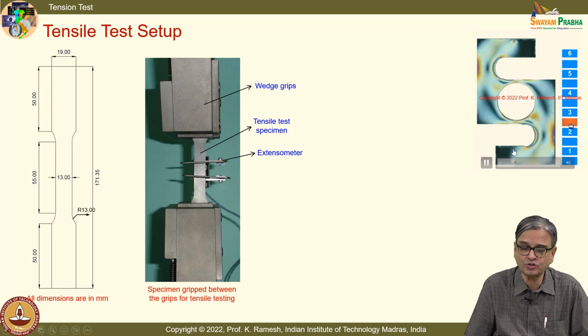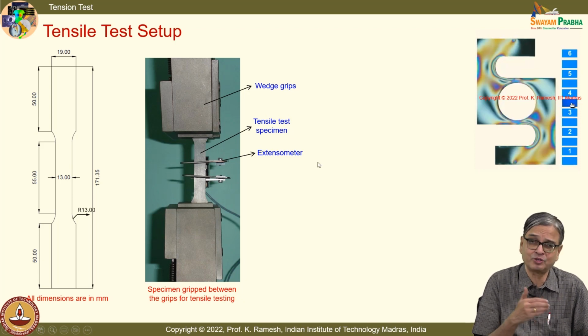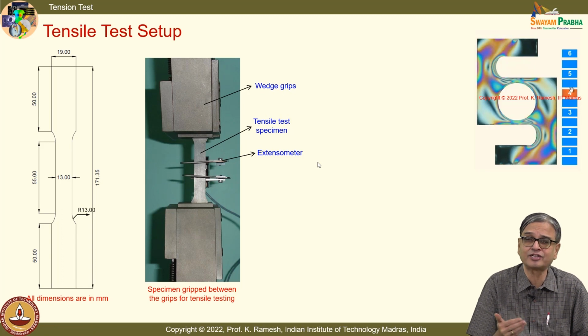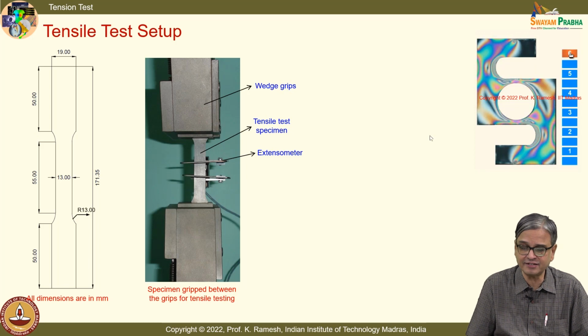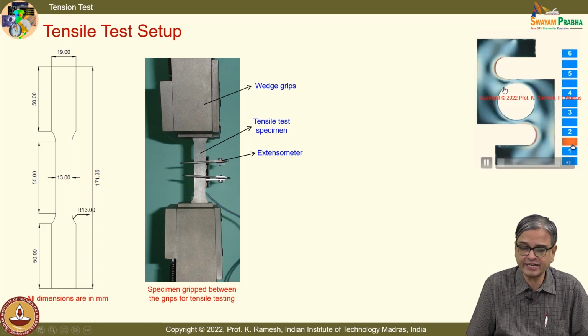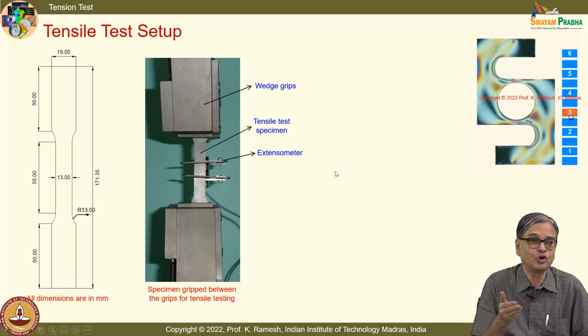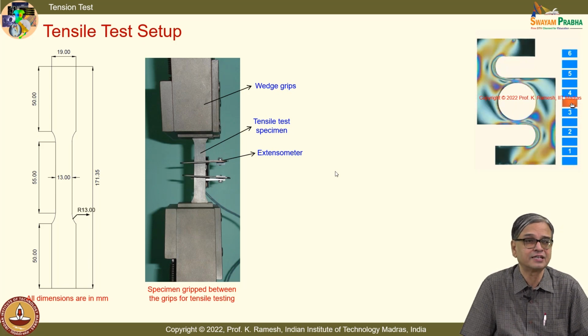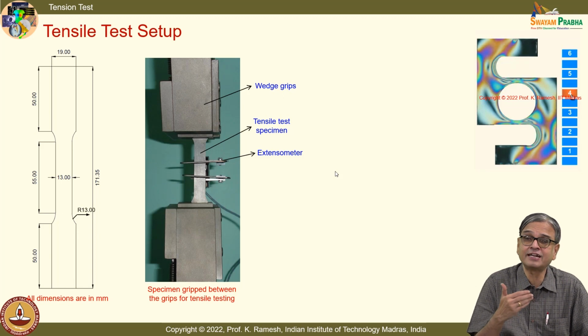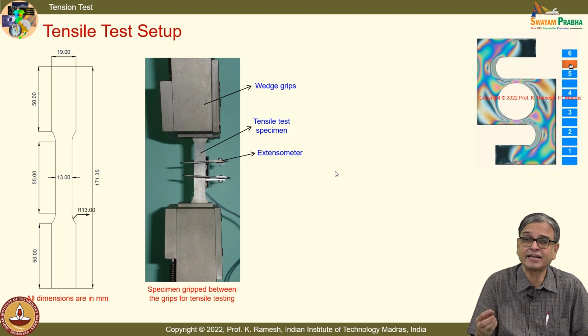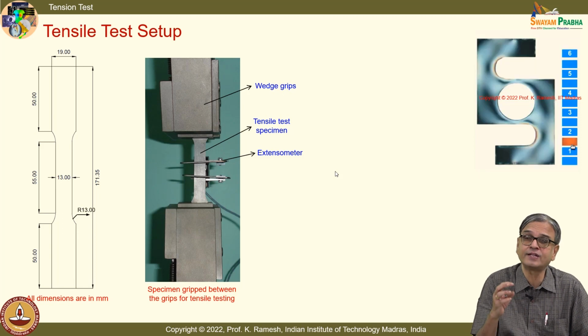When it is subjected to loading, if you perform a test, because these are all not coming under your strength of materials, it's difficult to analyze what is the stress state in this. They put 4 strain gauges, 1, 2, 3, 4 on the inner boundary of this. Because we have discussed, we want to amplify the signal in the case of transducers. So, if I put 4 strain gauges, I can get 4 times the signal when the load is applied.